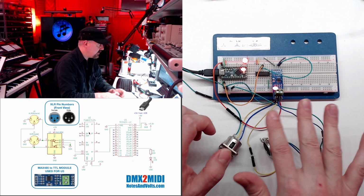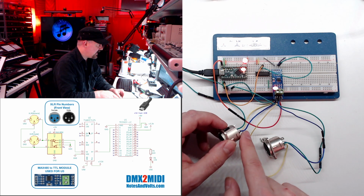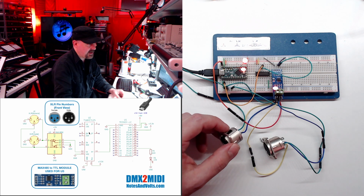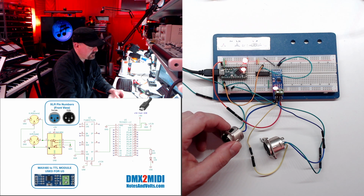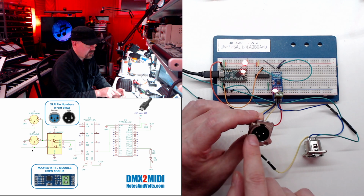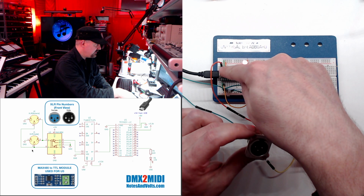So now that we've powered up our chip with 5 volts and ground, I have to connect the 2 data lines to the B and A inputs. If you look at our diagram here, pin 3, which is the bottom pin, is going to go into the A input, and pin 2 is going to go into B. Pin 1 is ground, so that's going to go to the ground on our Teensy board, which